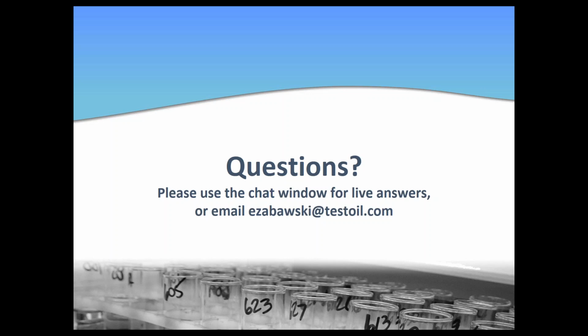Normally when we see all the ISO codes equal, they tend to be at very high values like 23 or 24, maybe even as high as 27 for that matter. What that typically indicates is you've maxed out the instrument that's performing the measurement. Basically all the codes are as high as possibly able to be measured.